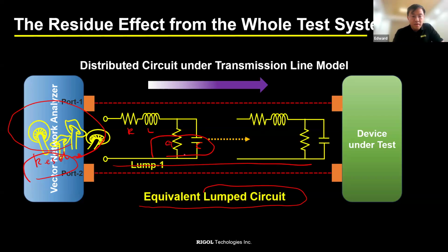So you can see this is lump 1 through lump 2N, right? We can calculate it by the wavelength of the traveling wave. Generally speaking, we use 1/6 of the wavelength to get the equivalent lumped circuit devices. To make the scale more certain, we use 1/10, which makes sure you get more accurate equivalent lumped circuit models. Okay.